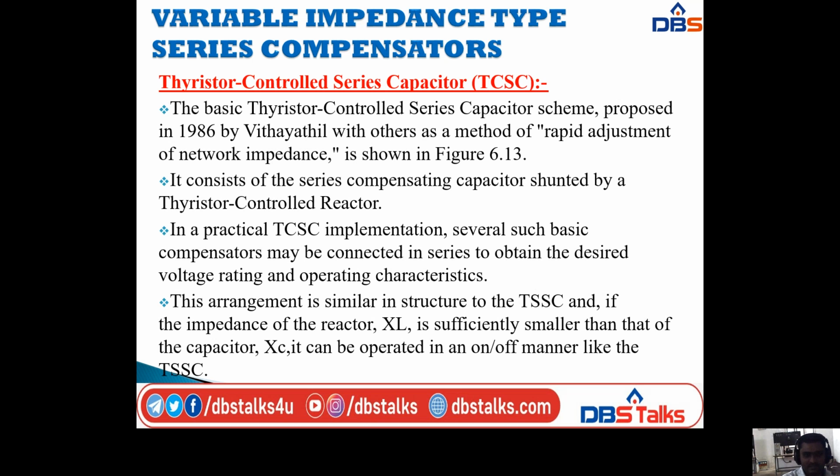So that means, from the diagram, it consists of the series compensating capacitor shunted by a thyristor controlled reactor. In a practical TCSC implementation, several such basic compensators may be connected in series to obtain the desired voltage rating and operating characteristics. That is a connection of the reactor and the capacitors.